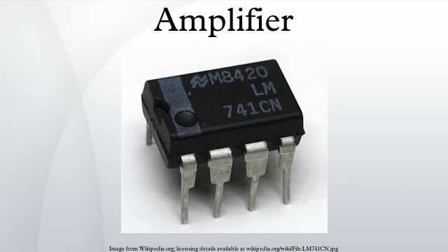Amplifiers designed to attach to a transmission line at input and/or output, especially RF amplifiers, do not fit into this classification approach. Rather than dealing with voltage or current individually, they ideally couple with an input and/or output impedance matched to the transmission line impedance, that is, match ratios of voltage to current. Many real RF amplifiers come close to this ideal. Although, for a given appropriate source and load impedance, RF amplifiers can be characterized as amplifying voltage or current, they fundamentally are amplifying power.